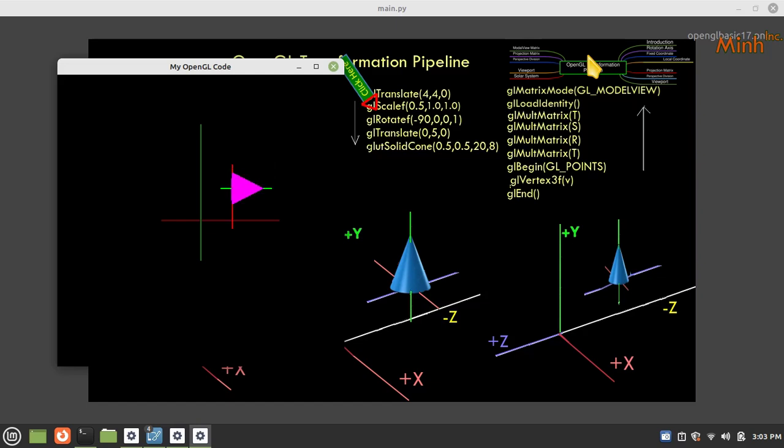Now we'll translate. If I press along the y axis, that is up, it will go in the new y-axis, not in the grand y-axis. Grand y-axis is going in this direction. The new y-axis is this. So I'll press 5 times: 1, 2, 3, 4, 5.